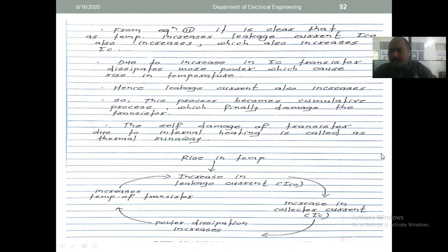See, due to the voltage or current flowing through the devices, what happens? There is an increase in the temperature of the collector base junction. It is nothing but a rise in temperature of that particular region. We have applied the input to the base and the output comes at the collector, so the related point is the collector and base. The temperature of the collector base junction increases when more and more current flows through the device.